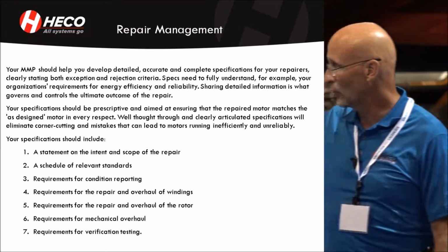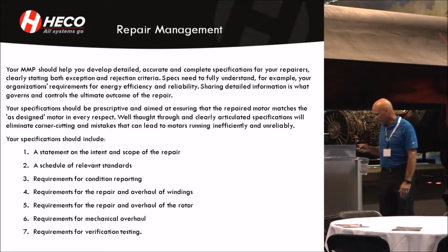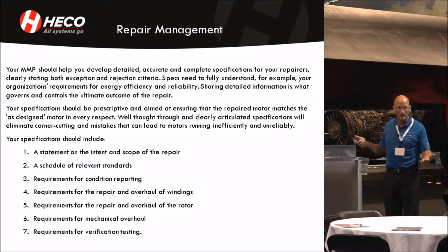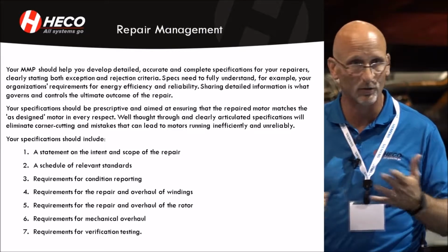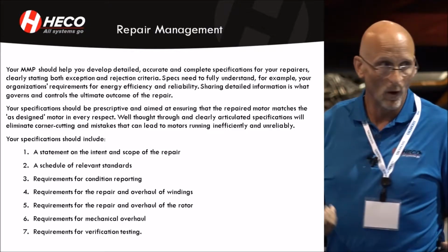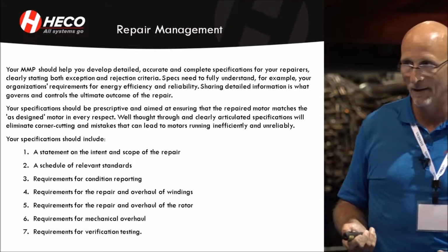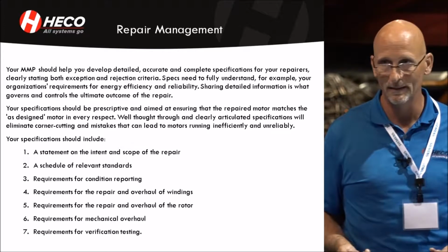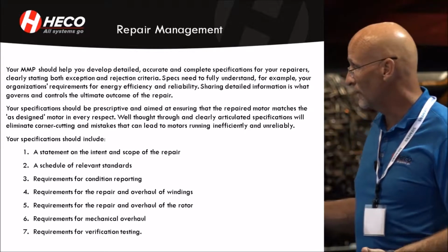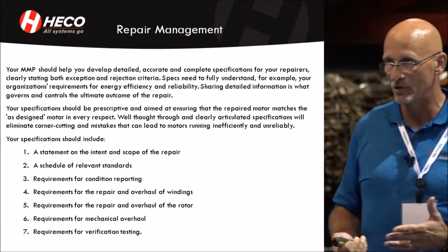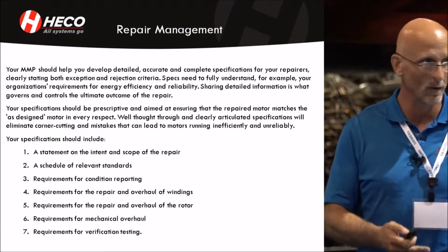What kind of standard? We break it into different categories: the intent of the repair, schedule, relative standards. Are you using IEEE, ESA, or NEMA standards, depending on what you're using? Requirements for condition reporting: what are they reporting to you? If you get a motor repaired, are you getting a report back, and what are they giving you? Do you know what they did? And then the requirements for the repair and overall winding. We find that if you're not detailed enough, you're not going to have the information to really pin down what they are doing for you.